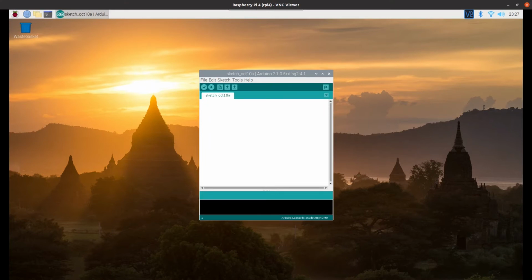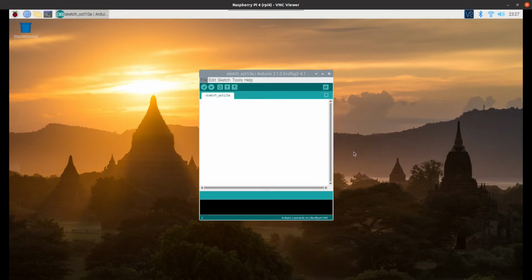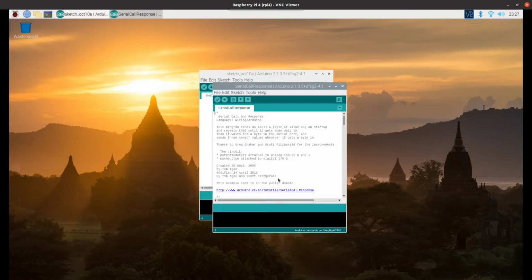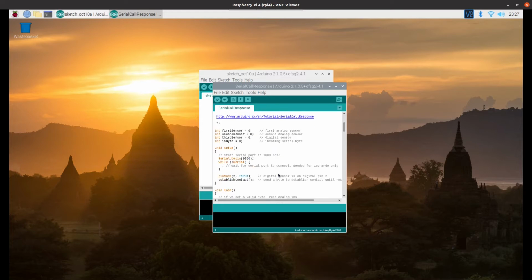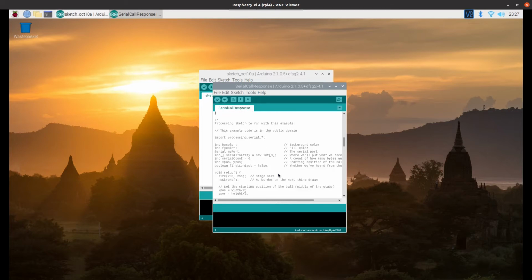The Arduino IDE includes some sample code for serial communications. The code provided here is used to send a single byte back and forth, but it's quite limiting. It's okay if you're looking at the status of a single pin, say, and you could expand it so it could pass a series of codes back and forth. But instead, I wanted to use text instructions with appropriate responses. Whilst not as efficient, it's useful when trying to debug as it means you can do some testing through the serial monitor, which I'll explain later in this video.